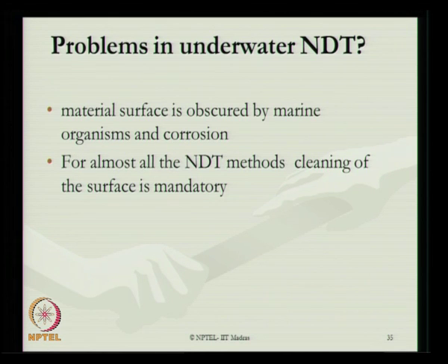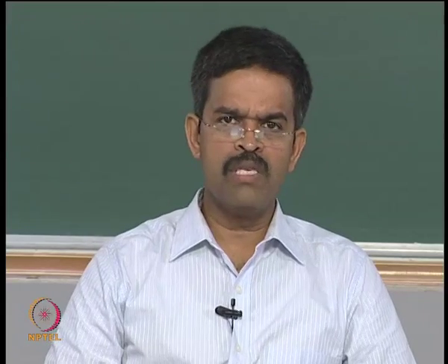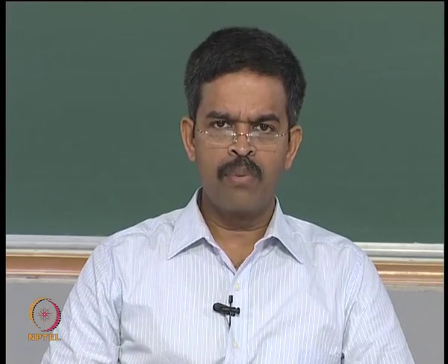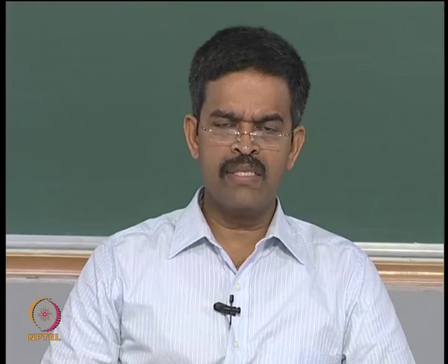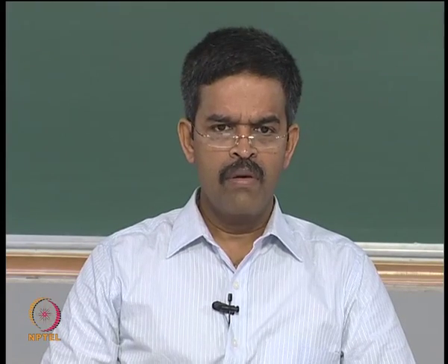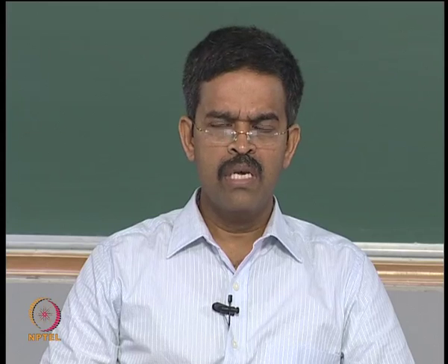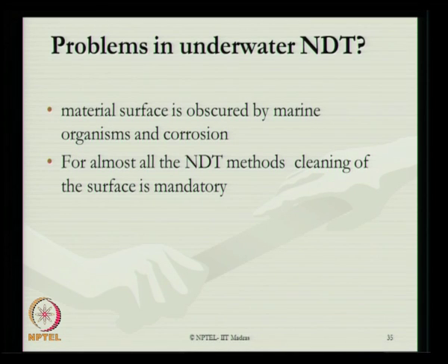There are some problems associated with NDT when you carry it out underwater. The material surface is obscured by marine organisms and corrosion products which are formed on the surface of the member. So, these formations generally prevent and protect the members from being accessed for any inspection. For almost all NDT methods, surface preparation is very important. Cleaning of the surface becomes mandatory if you want to successfully employ any of the NDT methods for members which are underwater.